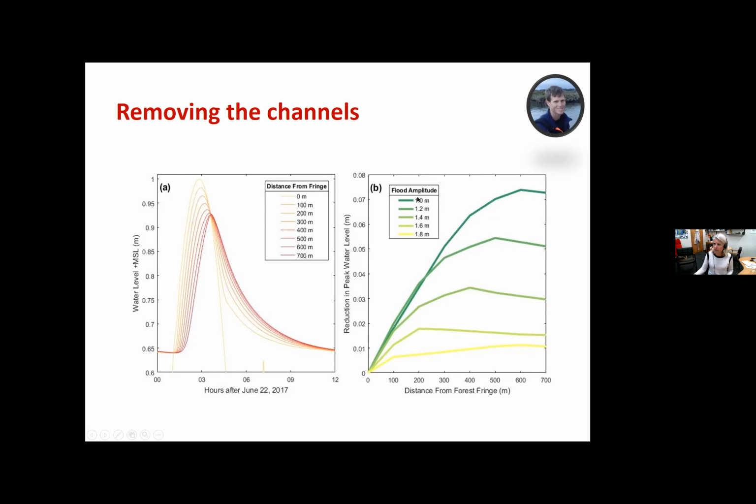When the flood wave was quite small, this dark green one, it caused a quite large reduction in the flood amplitude. But as you increased your surge size, the attenuation capacity of the mangroves got lower and lower and lower. You see some people saying that the effect of mangroves on storm surges is a 20% reduction per kilometer, and then they extrapolate that to larger and larger storm events or storm surges, but it's not actually true. They behave very differently depending on the size of the surge.